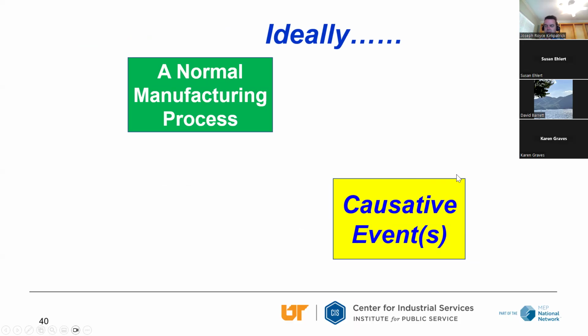You guys that are in the automotive world, what document do we have that indicates what causes defects? Anybody? Your FMEA. Your FMEA should be a document that we utilize when we have failures and complaints. That's where we should almost always start when we have a manufacturing type defect or a manufacturing complaint.